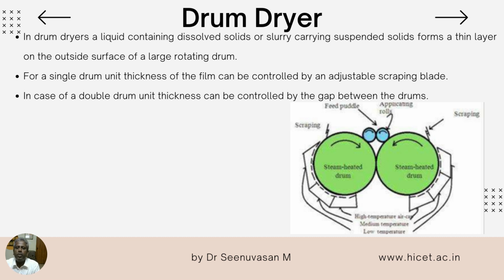The design of the components is similar to that of the drum filter. The knife may be held just against the surface. It may be brought closer by turning the adjusting wheels. The knife supports may be turned through part of a circle so that the angle of the blade of the knife relative to the drum surface may be selected for the greatest shearing effect.